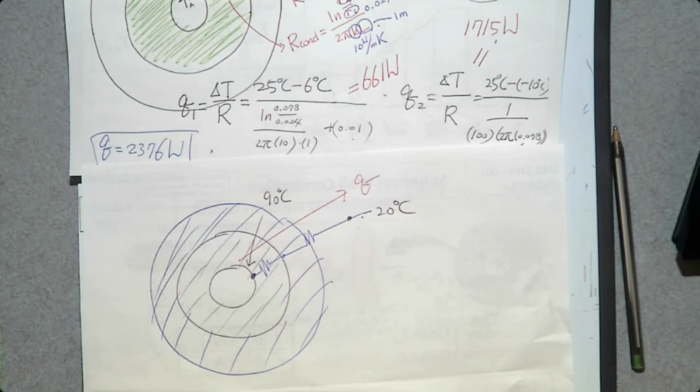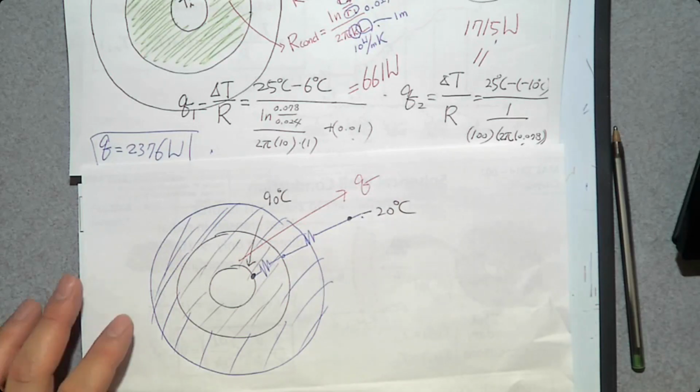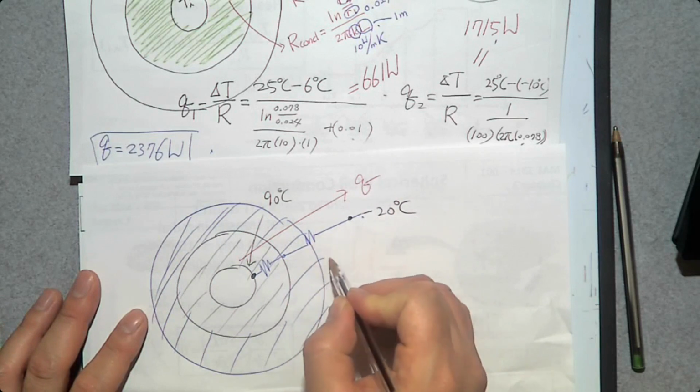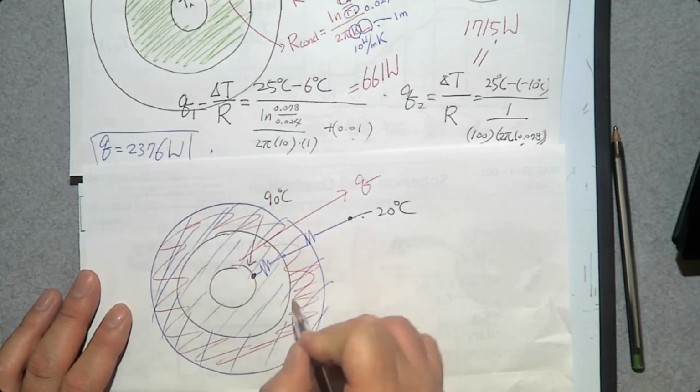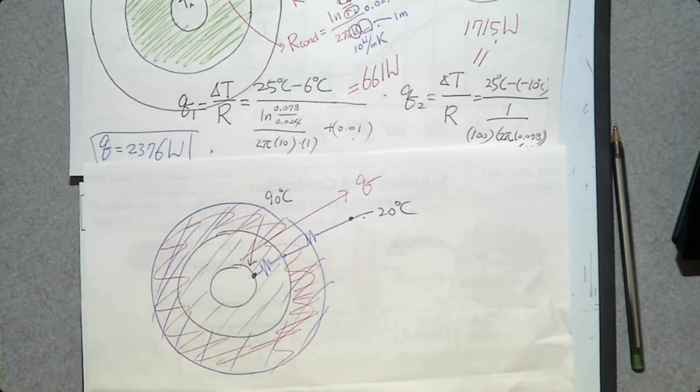Why is that? When you add the insulation, we add the insulation to decrease the rate of heat transfer. But the rate of heat transfer does not always go down. There is a threshold. When you add the insulation, what's going to happen? If you add the insulation about this much, why does adding the insulation decrease the rate of heat transfer?